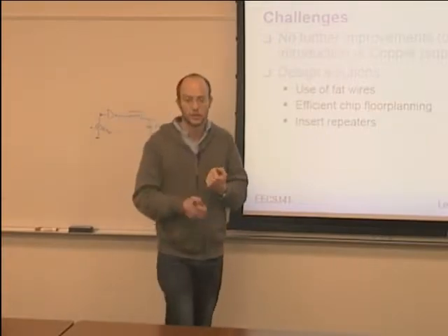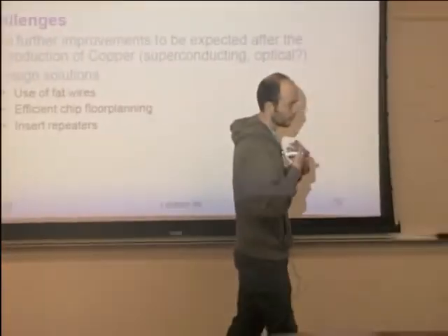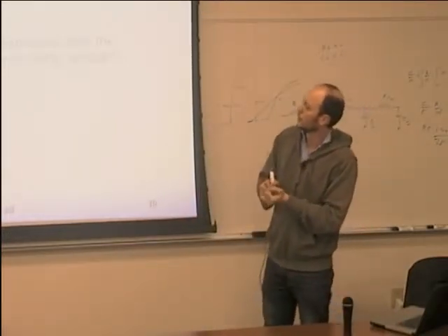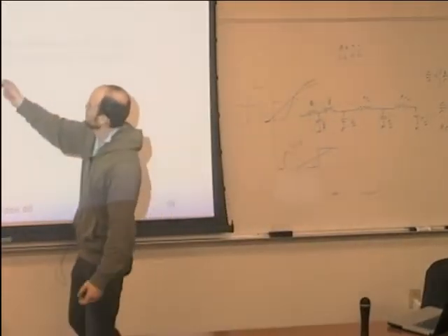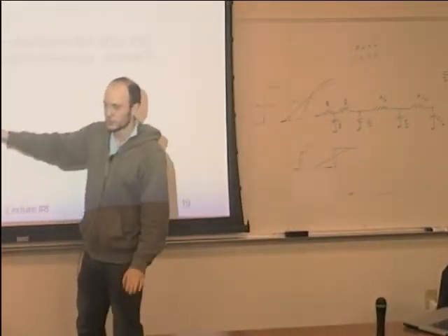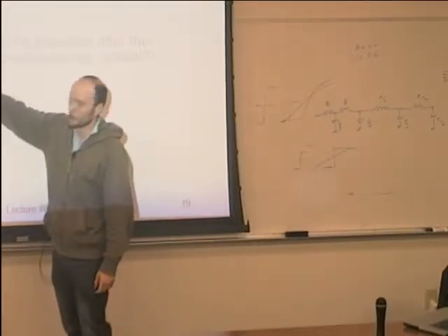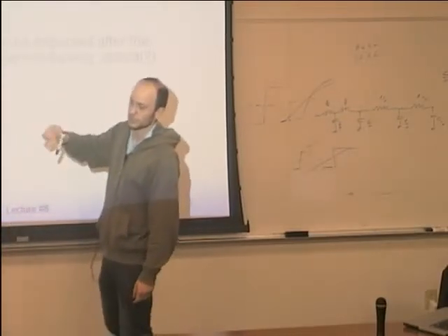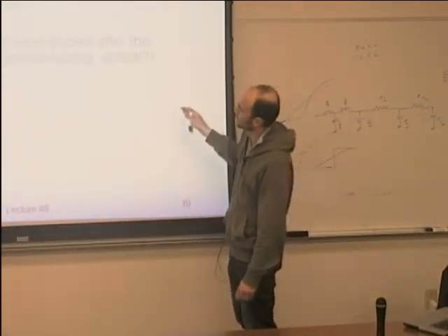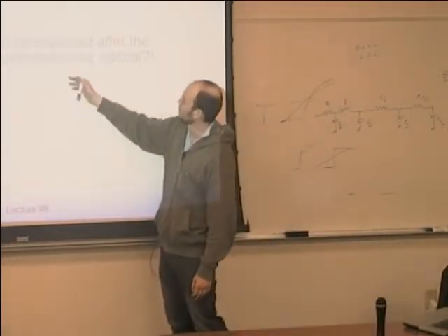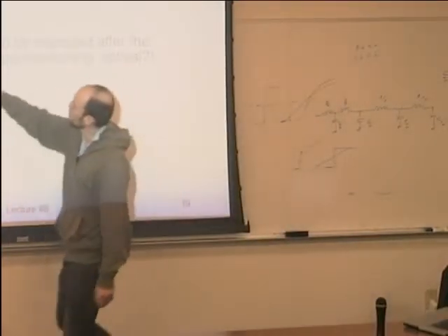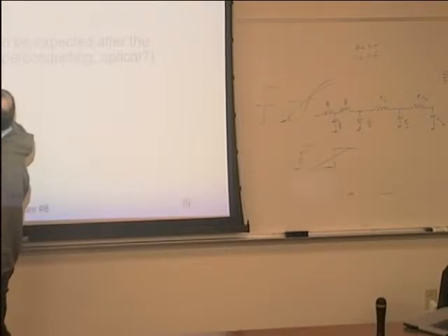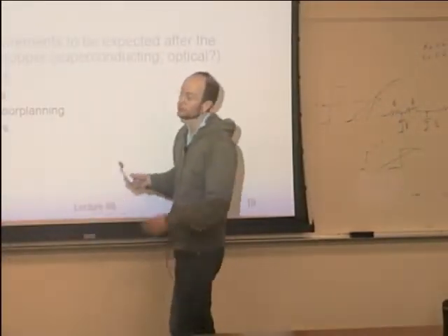So there's a few things that you can do. This is pretty interesting because copper is essentially the only low-hanging fruit in this space. Copper, we know how to deposit, so we do it. It's pretty much the lowest resistivity material that we can cheaply get. What can you do? You want to reduce this product, and essentially you can only do it for real by reducing the resistivity.